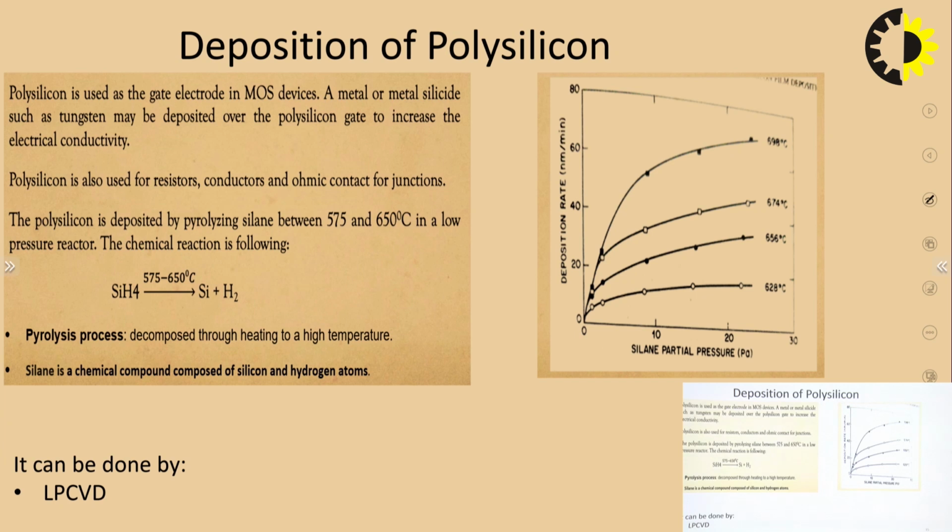First of all, deposition of polysilicon. Polysilicon is used in most devices. It can be used in transistors, for example to create the ohmic contacts. So such polysilicon deposition is quite important. This polysilicon deposition is done by the APCVD method.